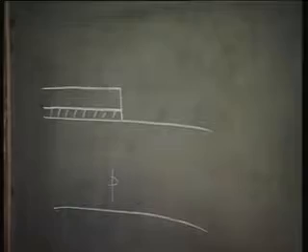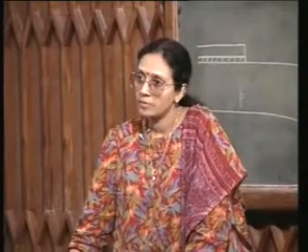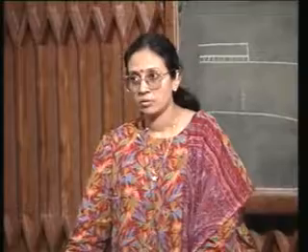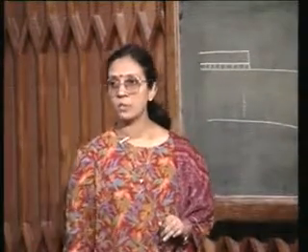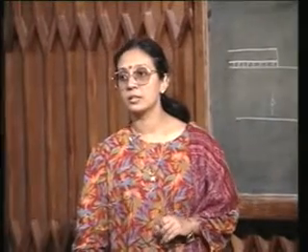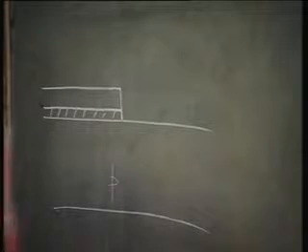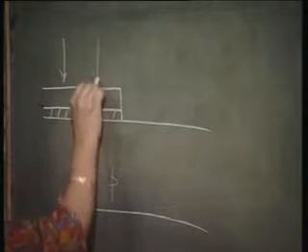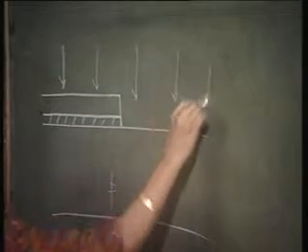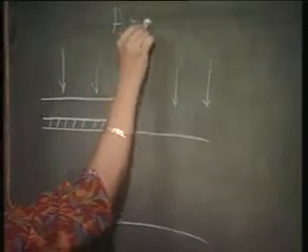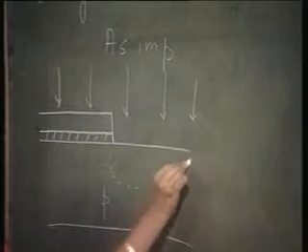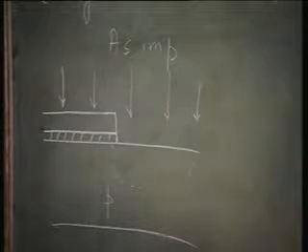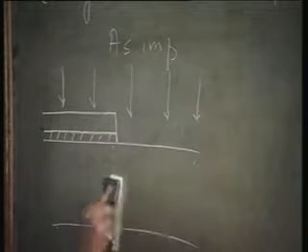One uses arsenic for this blanket implantation, because you remember that for all buried layers you prefer arsenic or antimony rather than phosphorus, because phosphorus will go deep. It actually should not be so deep, so I should have a thinner region, never mind.